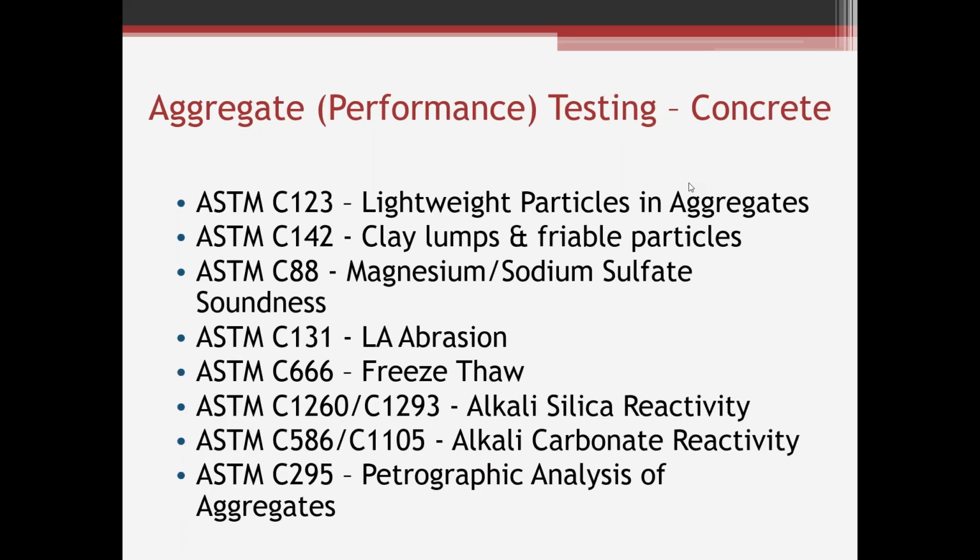So here's a handful of different aggregate performance tests. A lot of these are referenced in ASTM C33, which is a specification for concrete aggregates. C123 lightweight particles, C142 clay lumps and friables. I'll talk about each one of these individually. Some of them I'll spend a little bit more time on than others.